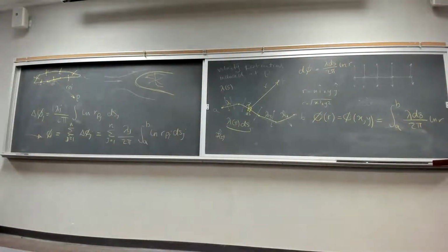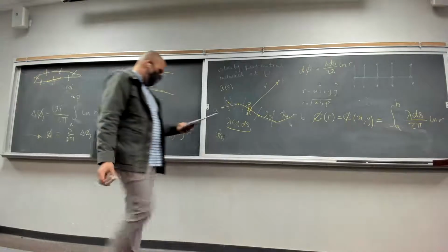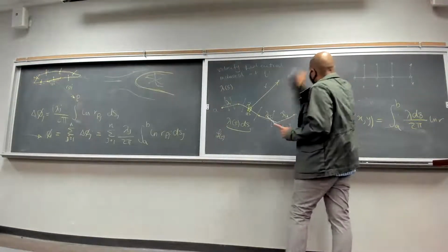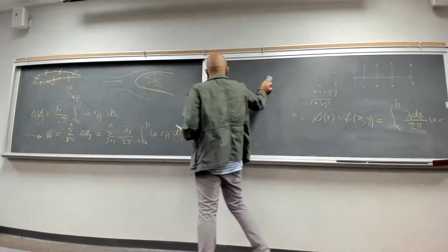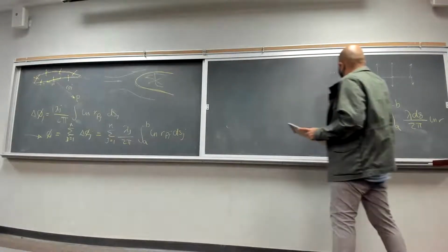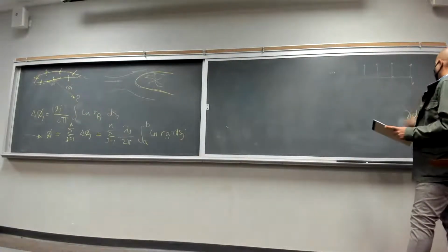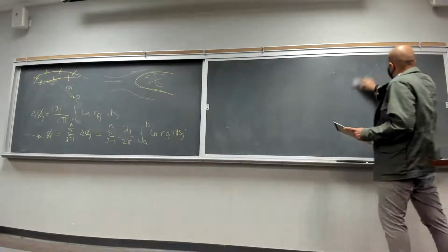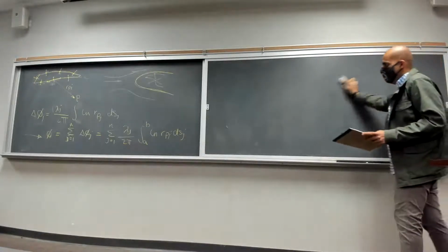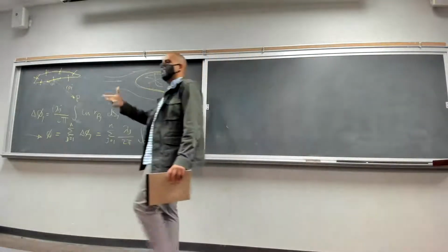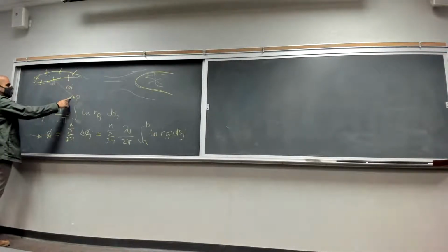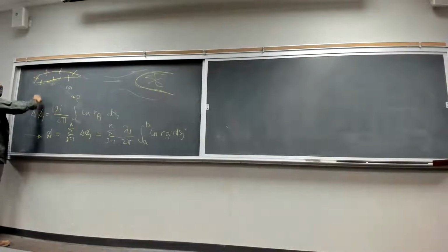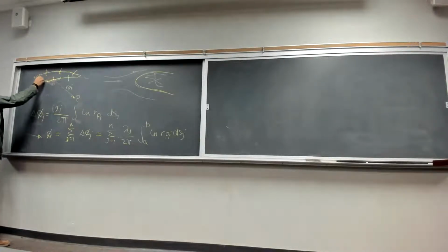So do we have any other questions? Okay. So we have the velocity potential induced by a couple of panels on a point P that is not necessarily on the panels themselves. But the next step, since we only care about what's happening on the surface of the airfoil, because we want to mimic the surface of an airfoil in our flow analysis, we want to find the velocity induced by, let's say, this panel on the other panel that is here.